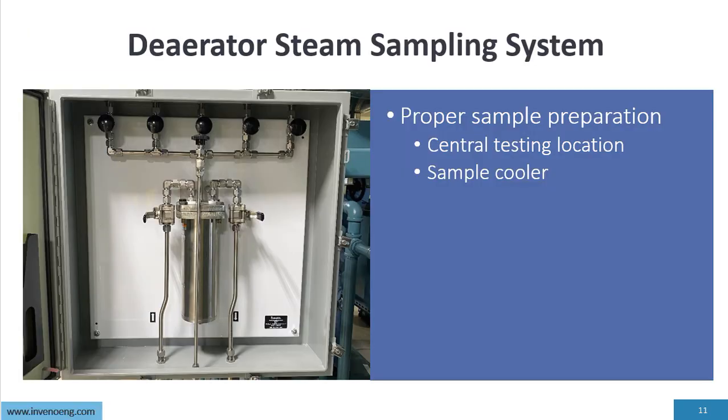The other thing for deaerator sampling, or doing the test for dissolved oxygen, is that you have to have proper sample preparation. Typically, the best is a central testing location and a proper sample cooler. The other thing is making sure that all the valve components meet B31.1.